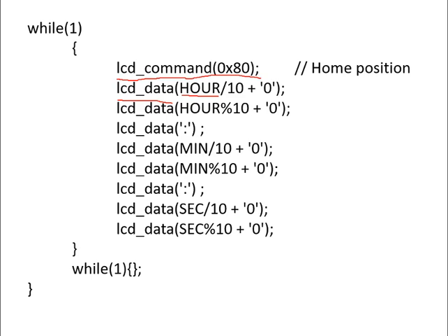So it will read the data from the R and it will divide it by 10 and it will send it to the LCD. Here it is mod 10. What do you mean by this? It is converting it into decimal value. Okay, hex to decimal. This is converting it from hex to decimal, and that number is displayed on the LCD.